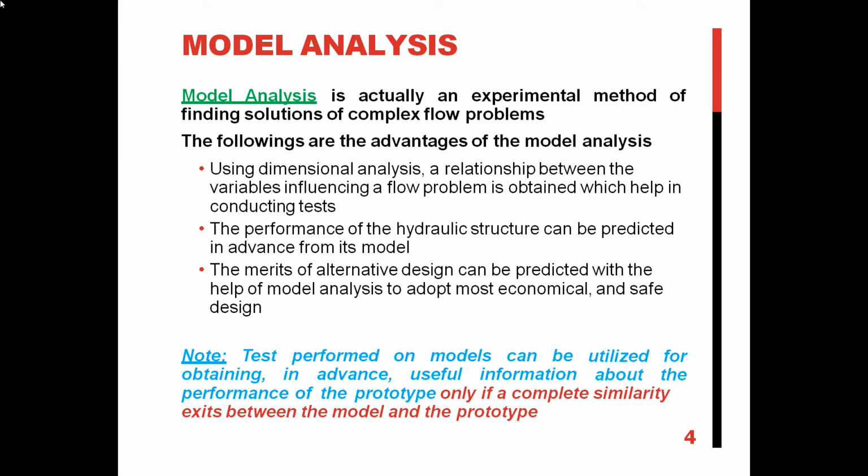Model analysis, as we have already said, is the experimental method of finding solutions to complex flow problems. Some advantages of model analysis are: using dimensional analysis, a relationship between the variables influencing a flow problem is obtained. The performance of hydraulic structures can be predicted in advance from the model. The merits of alternative designs can be predicted with the help of model analysis.